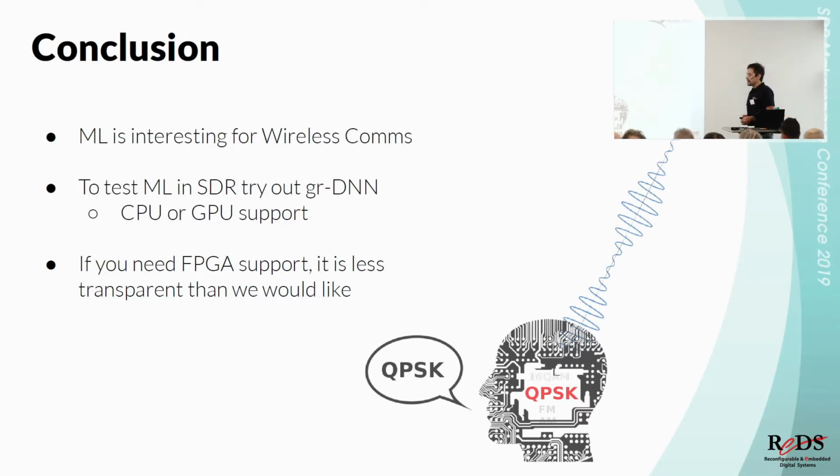But it's computationally intensive, and GPUs are not always available. And especially GPUs are super comfortable if you work with floating point numbers. But if we work with the other kind of data, fixed point, maybe 12, 14 bits from our ADCs, that's not the best in many, many terms.